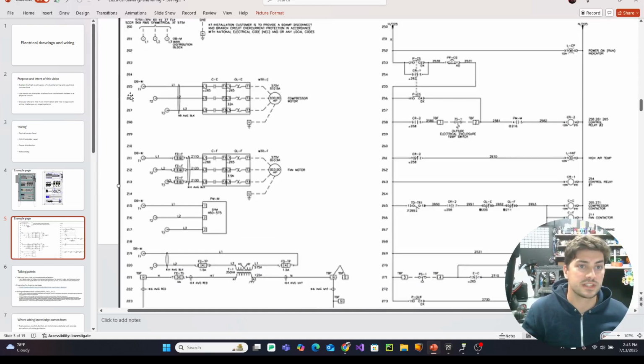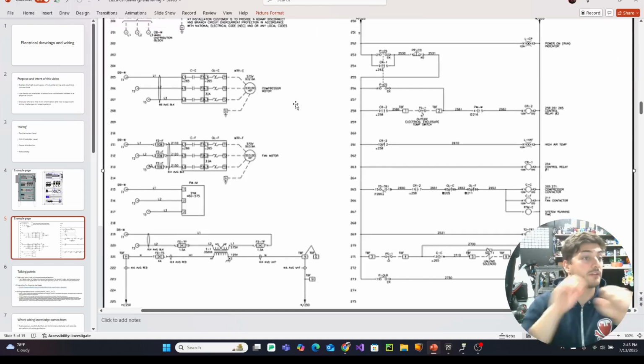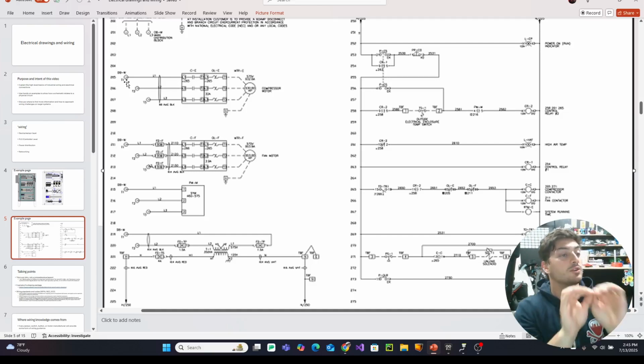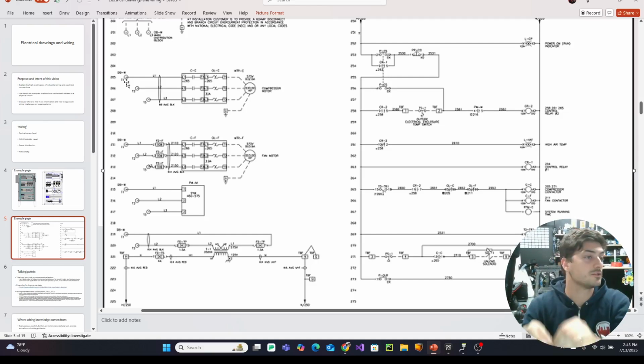That's kind of hard to see, but these line numbers from like 200 to 222, and often the wires will get physically labeled with whatever row they're on in their drawing package. So it's very normal to see a wire label physically on a wire in a panel that says 205 or 225. It's also very normal to see their tag name.